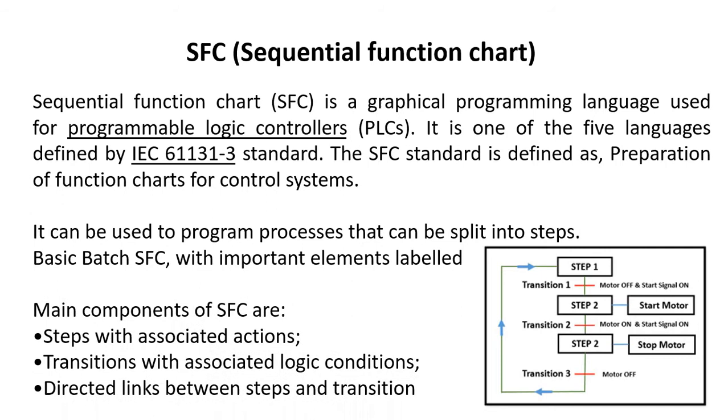The basic SFC has three important elements. First element is the step, which is associated with actions. Second element is the transition, which is associated with a logic condition. Third element is directed links, which join both the transition as well as the step.